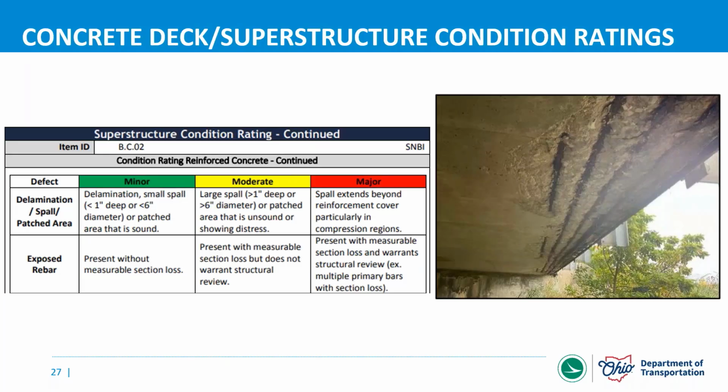So, a case like this, we see in the picture, very, very common to see slab or deck edges with CS4 or major deficiencies because of drainage issues. If we see something like that, we want it accurately rated as a major deficiency.